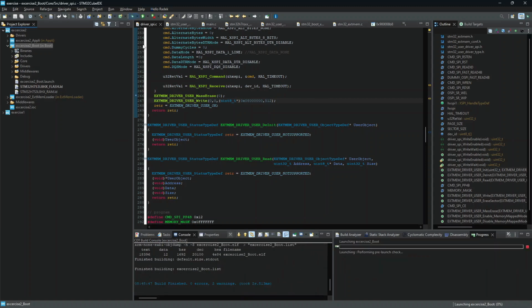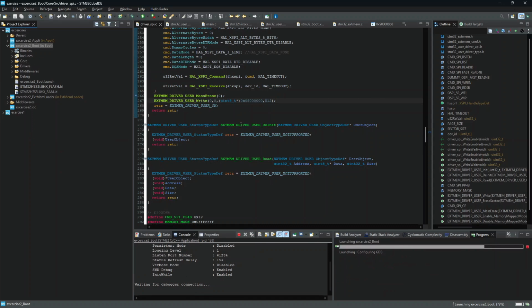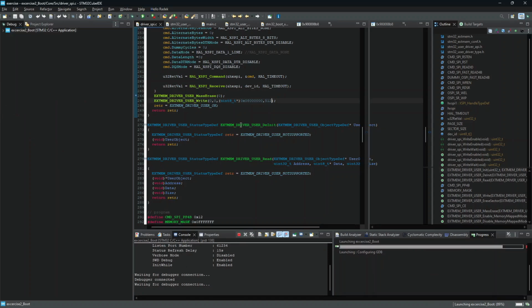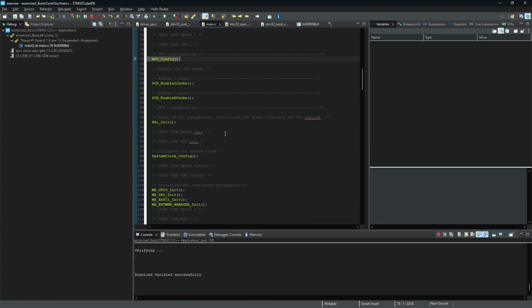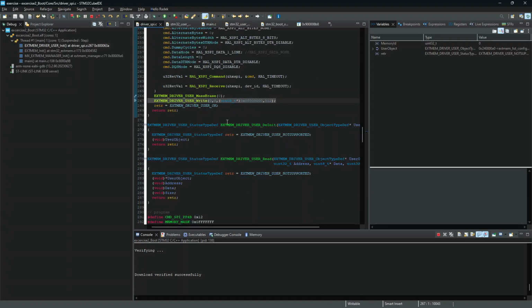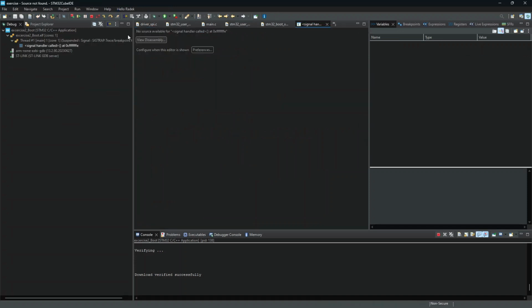I can run the debug. Don't forget, if you want to write into the memory, the part of the memory needs to be always erased first. So if I switch first the programming and then the erasing, it will probably not work, because it is not able to rewrite the memory again. Okay, I left the function, so I can go into the memory map mode.